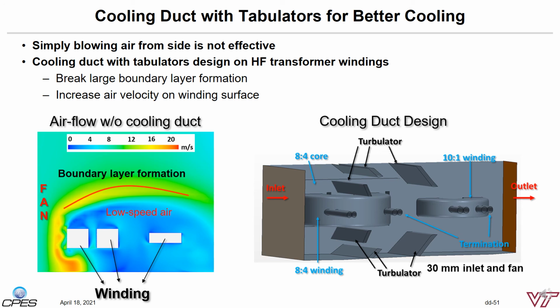The disturbed air molecules around the front surface of the winding will in turn slow down the flow just above them. This creates a thin layer of air fluid in which the velocity changes from free stream to zero. This layer is called the boundary layer. Within the boundary layer, the thermal transfer performance is little affected by the fan. Therefore, a good aero design will push the boundary layer very close to the surface of the winding to better exchange the heat flux from the winding to the airstream. The simulation result clearly shows a boundary layer formation in the design.